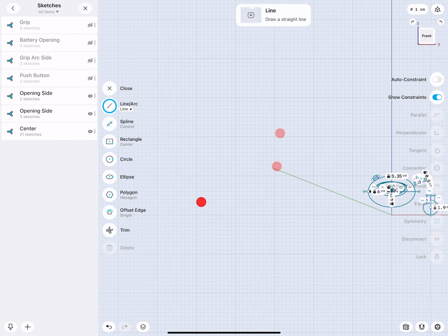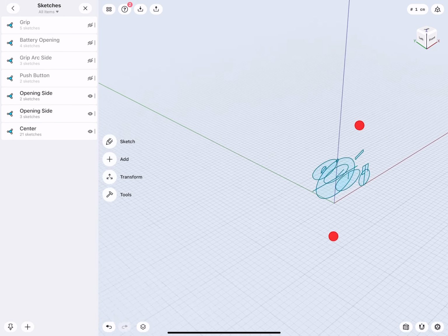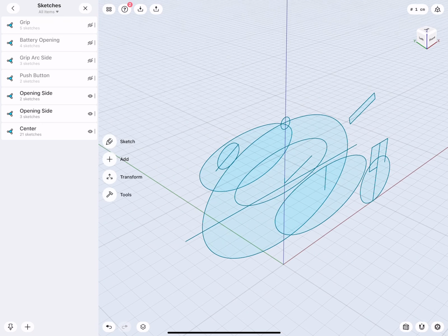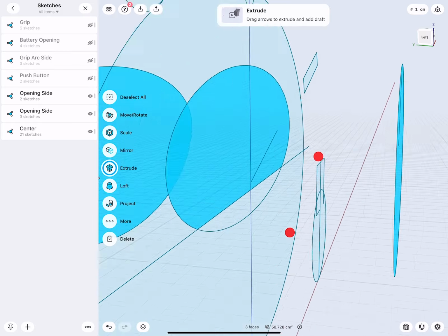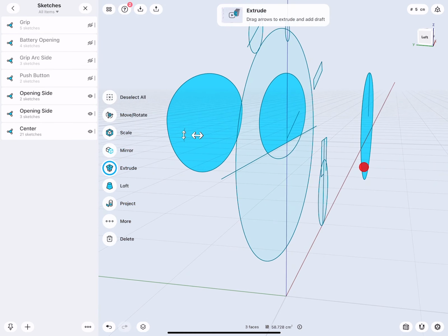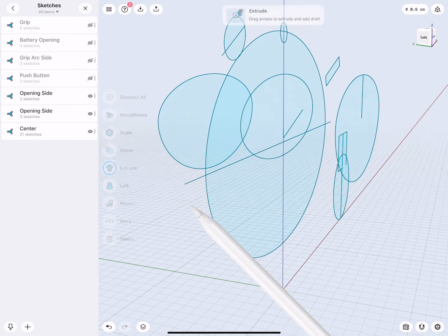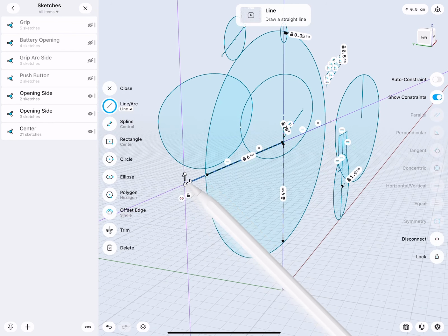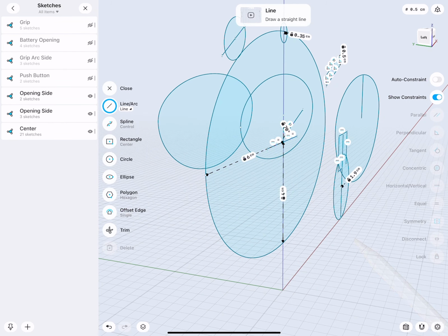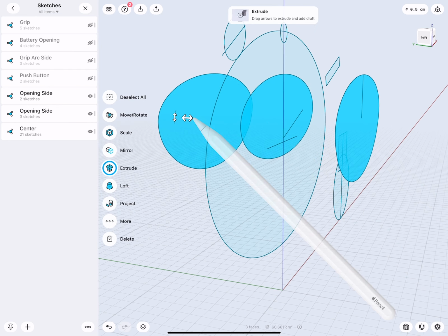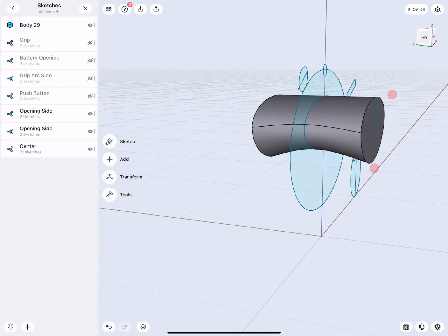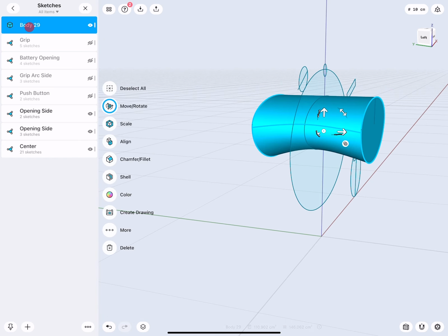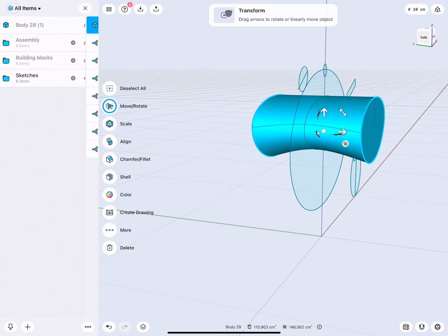Very good. Okay. Let's go back to our sketches. So here I would like from this to this to this, and there you see already we have the profile sliced. Again, that's the reason why I set this up. Simply move this back. Very good. There's no intersection and do a loft. Very nice.